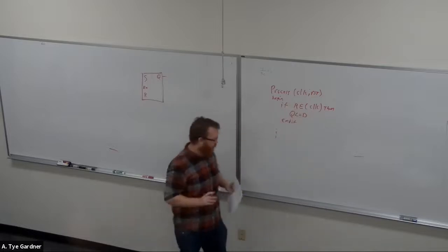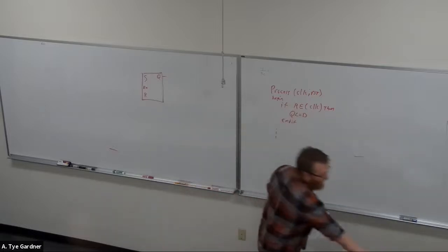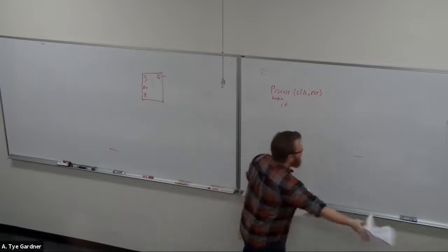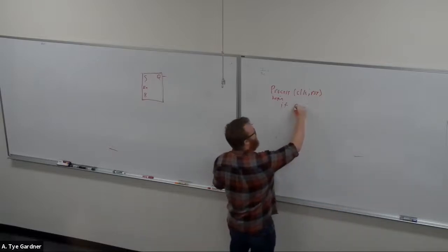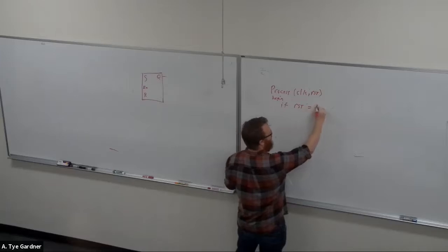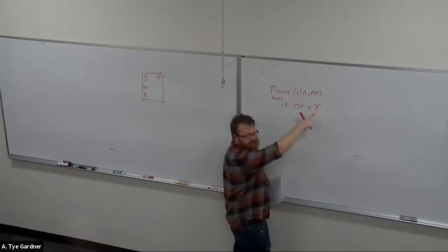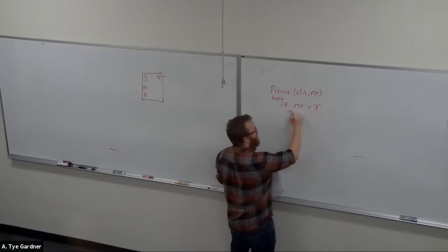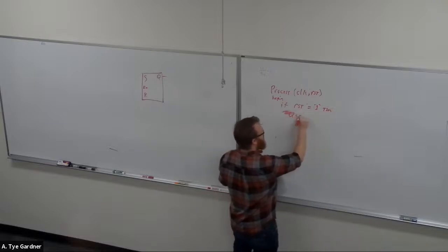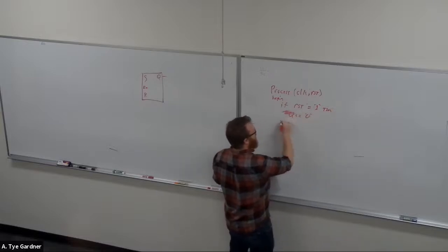So the way we tend to use those resets, which we'll get into more after the exam, is a slight change: if reset equals 1, so this is an active high reset, then Q gets assigned to 0.